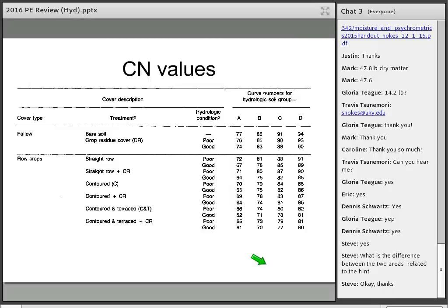So even though the surface is sandy, the subsurface was changing what the actual hydrologic soil group was for that particular soil series. So you can maybe do an estimate based on the texture, but you really have to look at the detail if you're gonna do the end calculations. And these are all tabulated somewhere for the soils you're dealing with.